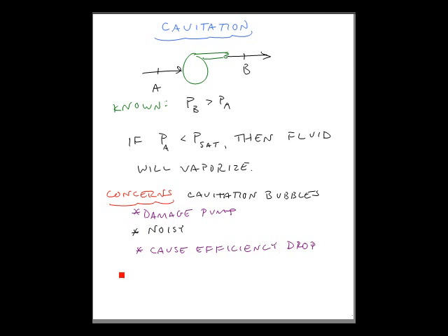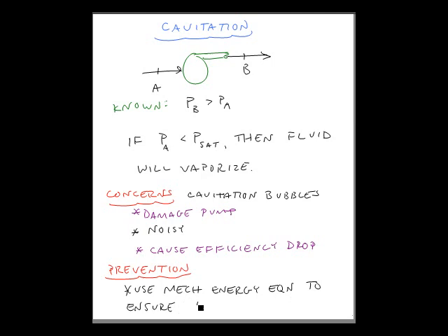How do you prevent it? Use the energy equation to ensure that my pressure at A is greater than my saturation pressure. So to avoid it, I'm going to use the energy equation to ensure the pressure at state A is greater than saturation.